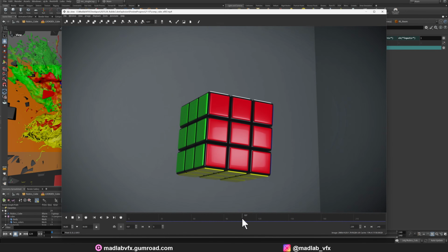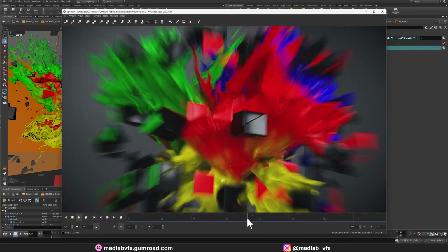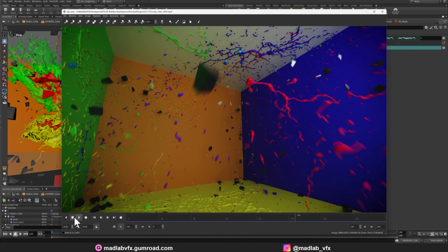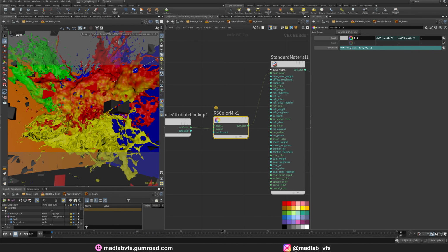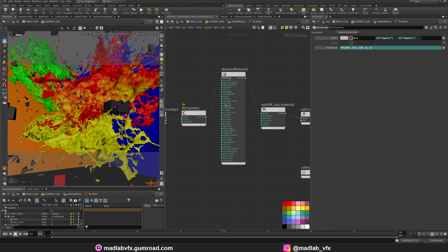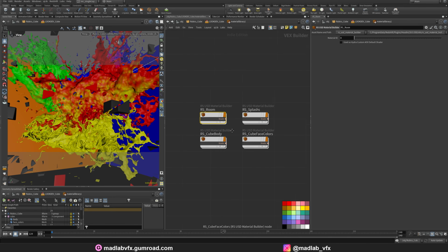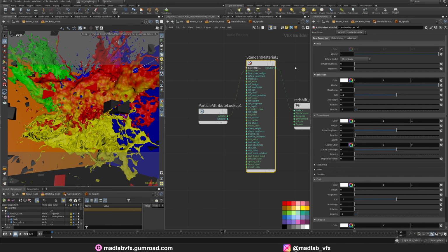I use, I think, frame 110 to 140, a LERP animation here. Inside the shaders, yes, I use the expression here to animate the blend colors from white to the colors, from frame 117 to 125. The splashes is just a simple shader using display color applied to base color with the roughness 0.